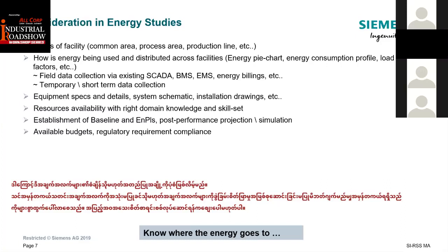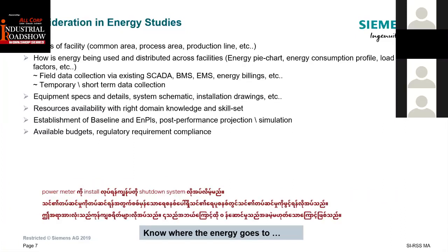That boils down a lot to how much budget is available. Conducting a full detailed audit is not cheap, because of the deployment of instrumentation by the service provider and the effort required, not just to purely get a temperature of the space. At times, we may even need to shut down a system to install a power meter, for example, or open up your installation on a hot water system or a chilled water system to install the instruments. All this requires cost, and that's why it will not be a free service.